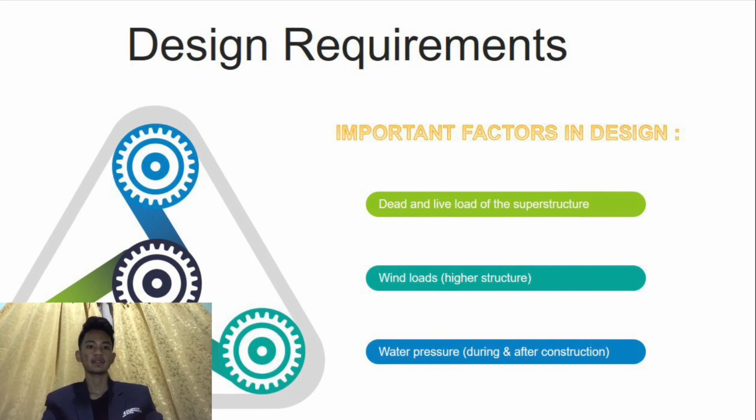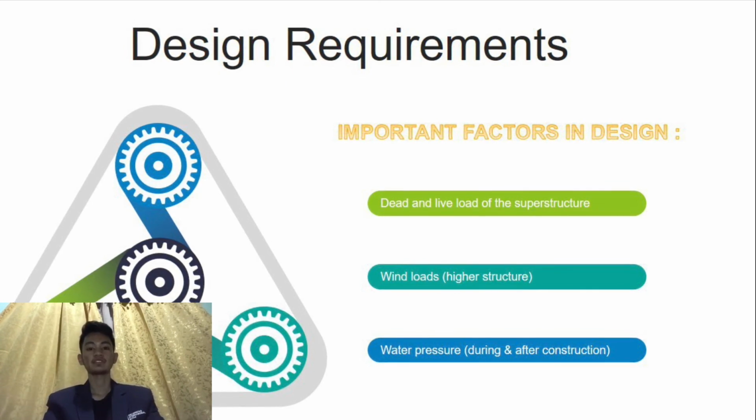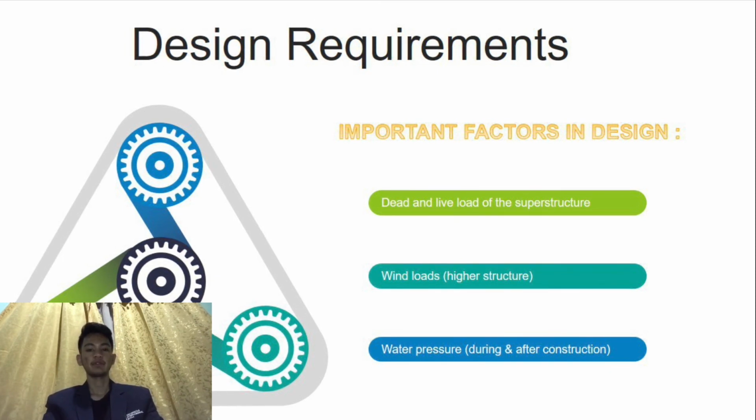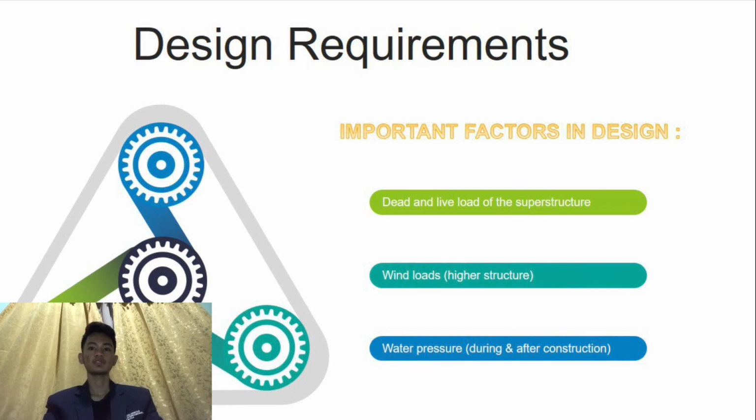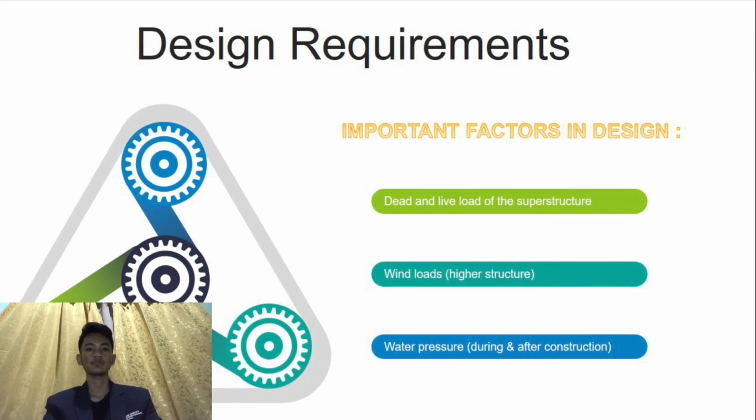A. Excessive water, use retaining wall. B. Water from below, pump out water, dewatering system. After construction, number 1. Continuous water pressure coming from the sides, cracks in wall. Therefore, the wall must be watertight. Reinforced concrete using design mix, massive thickness of concrete. Number 2. Continuous water from the underside, provide raft and sump.